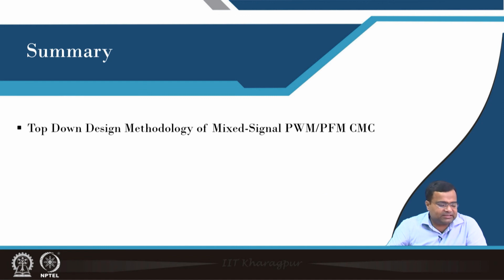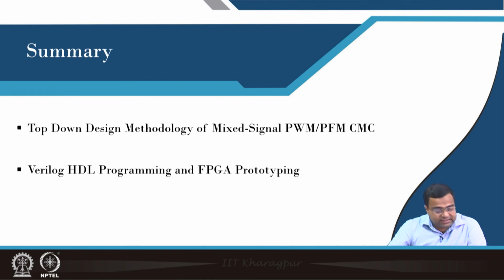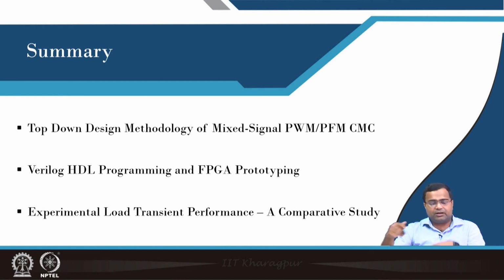So, in summary, we have discussed the top down design methodology of mixed signal peak current based PWM PFM control. We have synthesized this control technique using Verilog programming, and we have shown experimental load transient performance along with a comparative study of throughout PWM and multi-mode control.